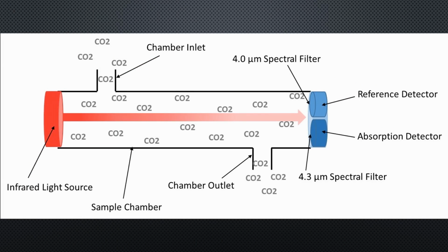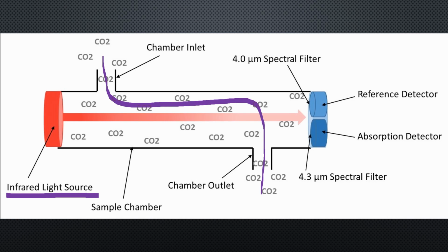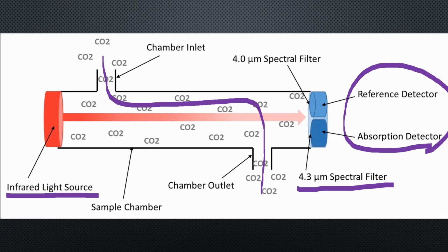Coming back to our topic, all current CO2 sensors work like that. They consist of a particular IR diode, a distance where the air can enter, and an IR detector, usually with a filter for 4.26 micrometers in front of the sensor. That's all. But because the CO2 levels are minimal, these parts must be produced in high precision.